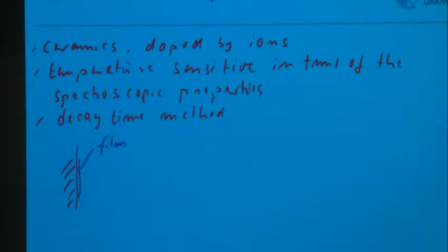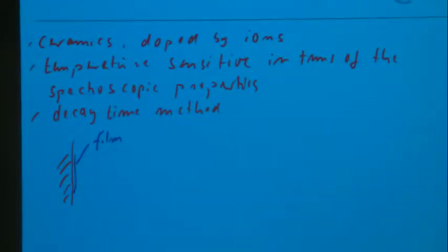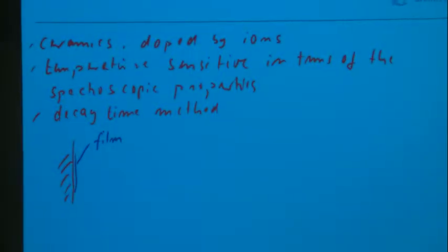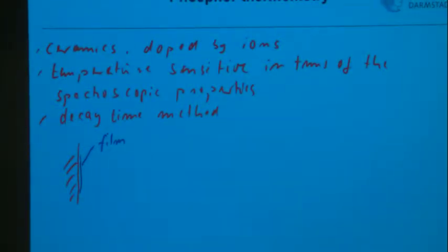And the idea is as follows. You have a surface. This surface is coated by a very thin film. This film contains the phosphor material. The easiest way to do that is an airbrush coating, meaning you have a high temperature resistant binder in which you put this powder of phosphor material, and then you use a laser, typically in the UV, to excite the phosphorescence, and then you have here a detector.